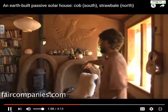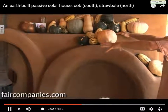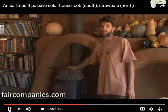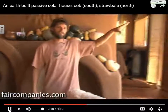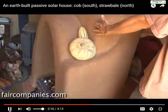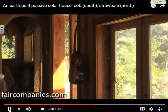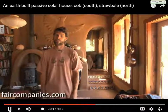And this interior wall here, this is cob up this high, and the cob is here for thermal mass. It absorbs heat from the wood stove when the wood stove's going. It also absorbs sunlight directly in the winter coming through these windows. The midday sun shines on this cob and heats it up. The earth provides a lot of thermal mass, which heats up very slowly and cools down very slowly.